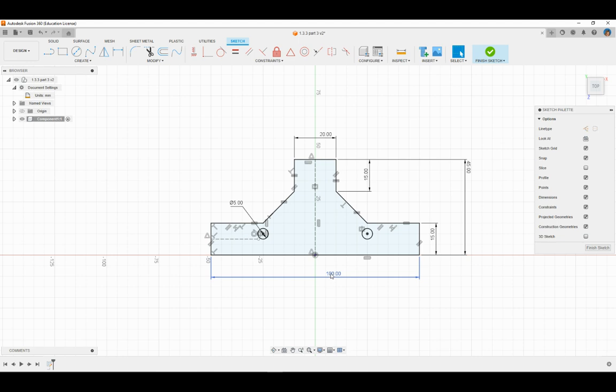Let's find out. Let's double click on the dimension, and I'm going to type in 125 and click Enter. And it did. If you have one side that got longer than the other, then you need to go back to part 3 and find out what happened with your dimensions, because something in here did not dimension correctly. Both sides of line 1 should have updated equally to give you a total of 125.